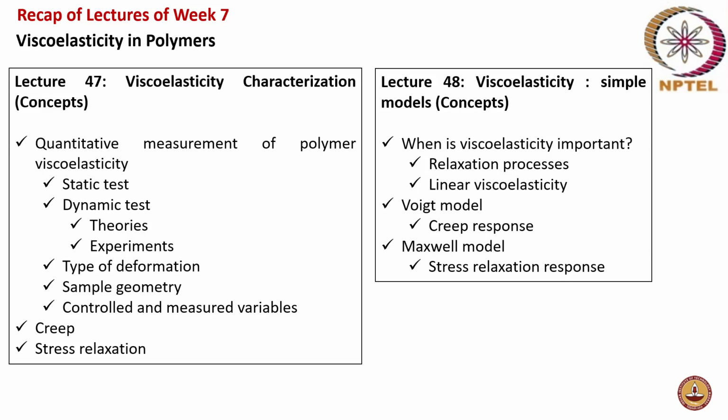Right. And if it is going to be a modulus, then for a viscous material, it is going to be 0, whereas it is going to be a constant value again for an elastic material. Right. And for a viscoelastic material, it is going to be a function of time. Right. And then